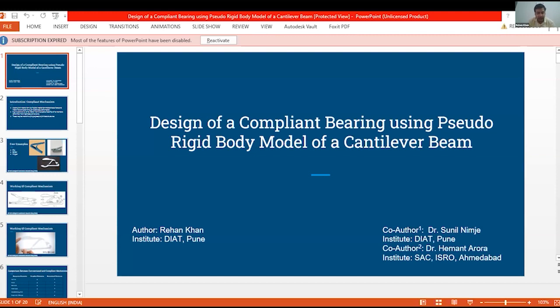As for the part count, the compliant mechanism can be made in a single piece only. Hence, very few parts will be present in the compliant mechanism. Again, manufacturing cost: since there is almost little to no assembly, we get a very low manufacturing cost for the compliant version of the same mechanism. And in terms of simplicity, due to the presence of flexures, conventional mechanisms have an advantage in that they are simple to design, but compliant mechanisms are a bit complex in terms of design.